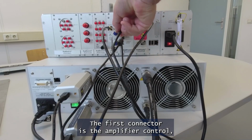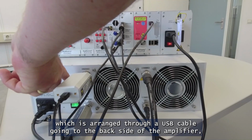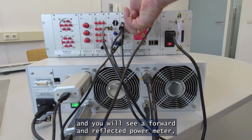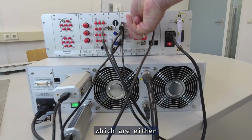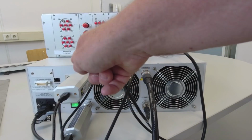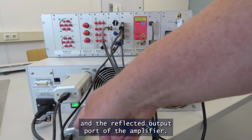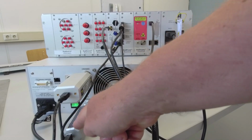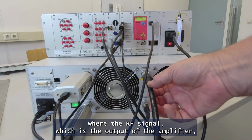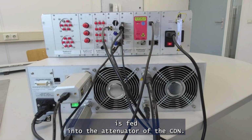The first connector is the amplifier control, which is arranged through a USB cable going to the backside of the amplifier. And you will see a forward and reflected power meter, which are connected to the forward output port of the internal directional coupler and the reflected output port of the amplifier. So this is basically the setup where the RF signal, which is the output of the amplifier, is fed into the attenuator of the CDN.